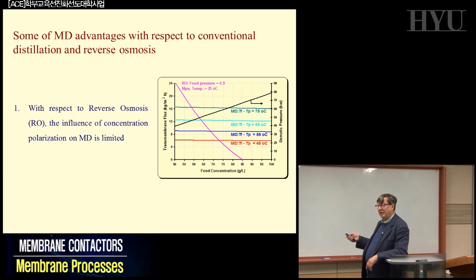No, this is a little bit more than 1 molar. The molar mass of sodium chloride is 58. So if you have 1 mole per liter, when you are around here, 60, you have basically 1 mole per liter. 85 will be 1.5, 1.6 mole per liter. Flux is zero if you don't increase the pressure significantly. You have to work with a feed pressure of 10, 20, 30, 50 atmosphere if you want to overcome this situation.